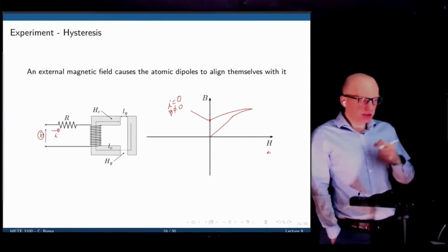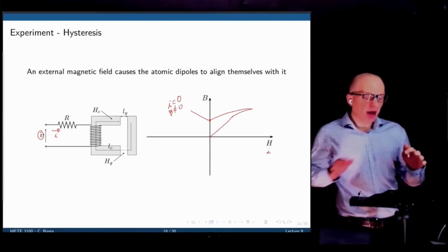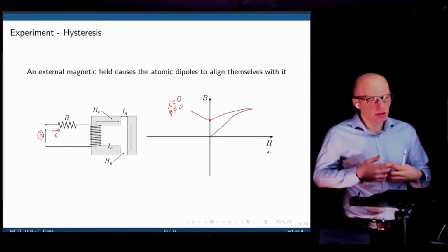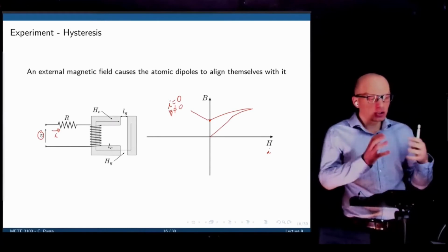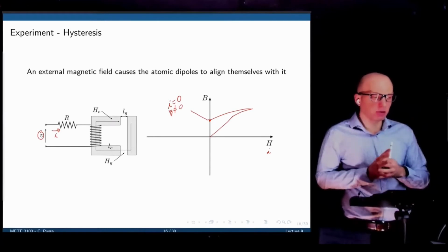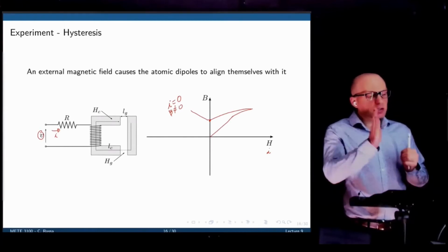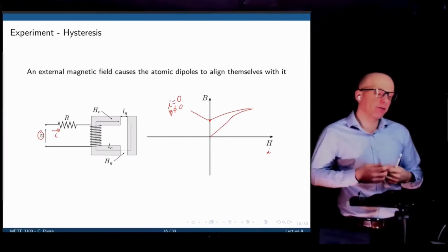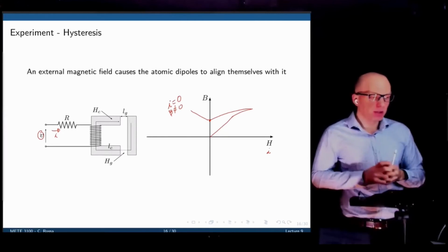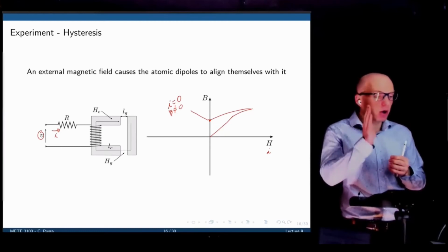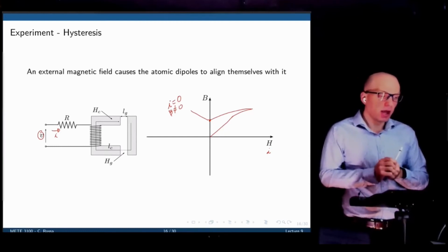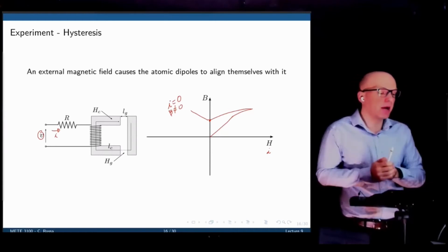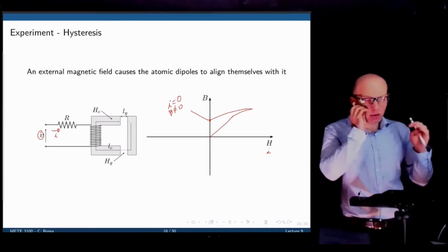What is happening here? This is the effect of hysteresis. When you have a ferromagnetic material and we apply a current to it, we create the magnetic flux density, and the dipoles of each element, each particle in the core, will now align itself with that magnetic flux density. And once we remove the external magnetic field, they remain aligned, all in the same direction, and they maintain some sort of magnetization. This now behaves as a permanent magnet to some extent. Of course, a weak permanent magnet.